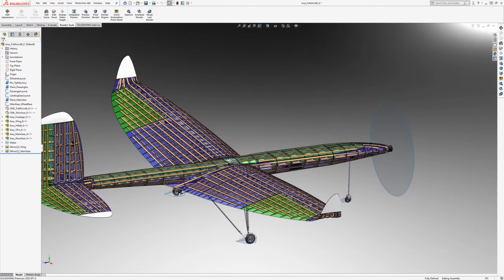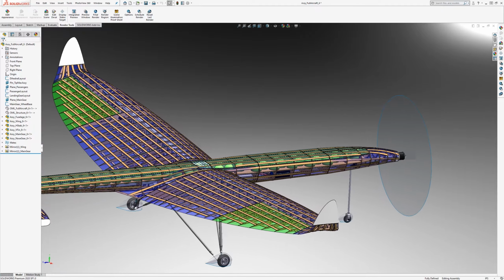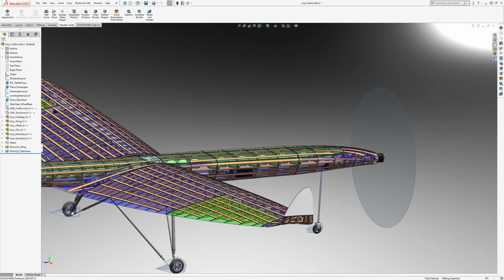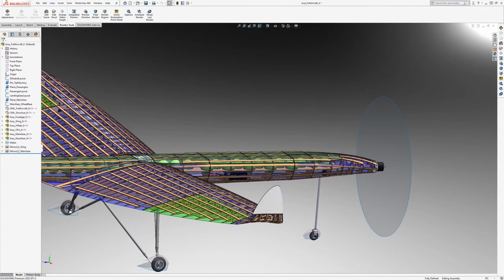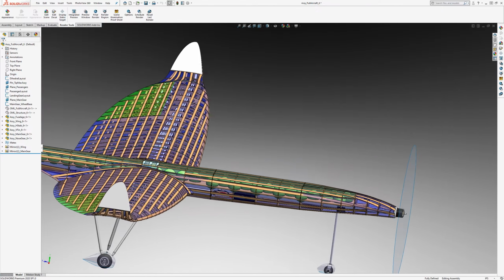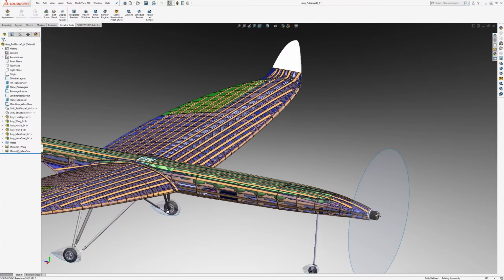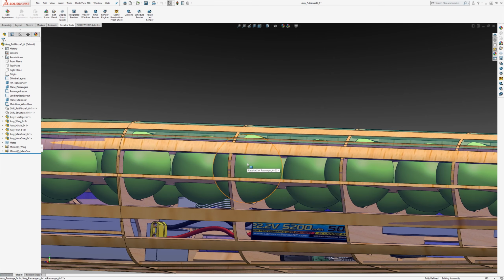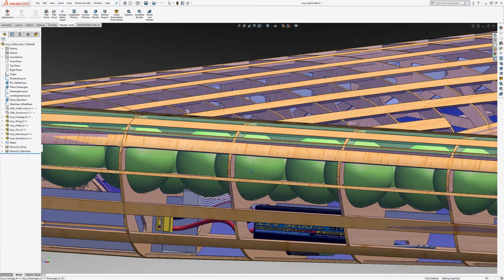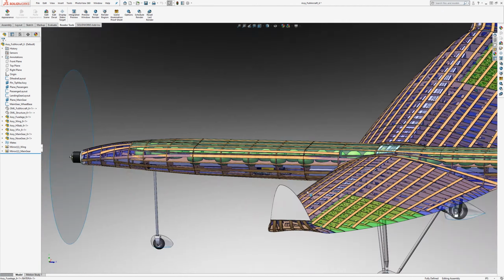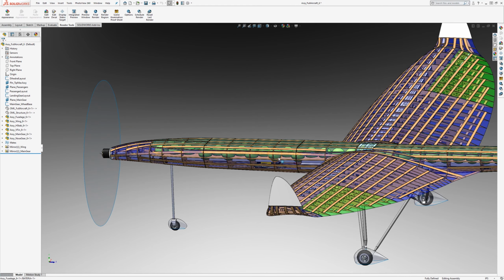Now, the structural layout of this aircraft includes an aluminum inner structure that accumulates loads and transports them throughout. And it also has a wooden outer structure that bridges local loads from the outer surface of the aircraft towards the closest inner structure. And it also supports lighter masses. It has mounts for them such as passengers, these are the tennis balls from the 2017 regular class rules, and batteries, we have the ESC, servos, hinges, things like that.